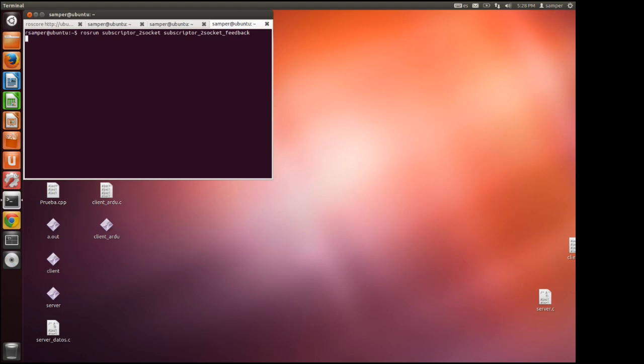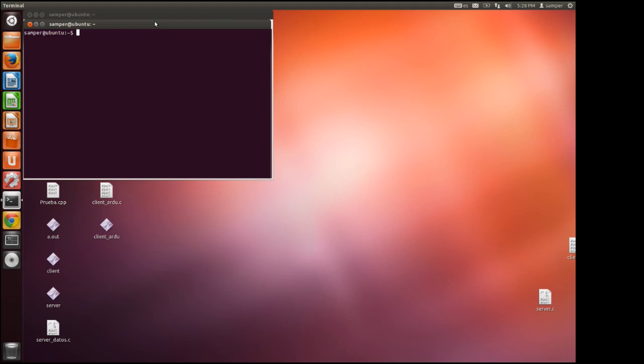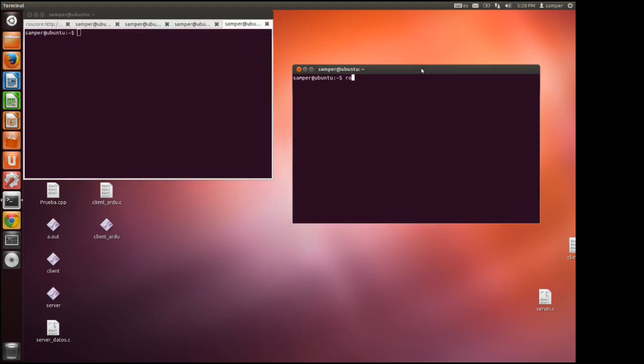The next step is to initialize the feedback subscriptor, which reacts to the feedback topic publishing. It could be used to generate reactive behaviors. In our case, it shows the warnings of the proximity sensor, obstacle detected or clear away, and also received and executed commands, just in order to keep a better communication and performance monitoring.